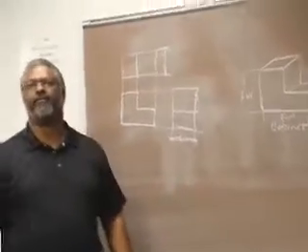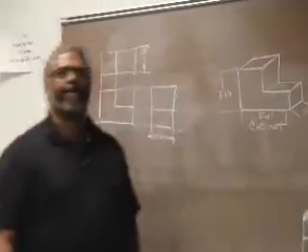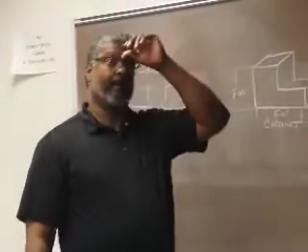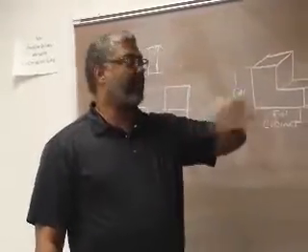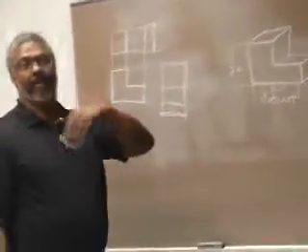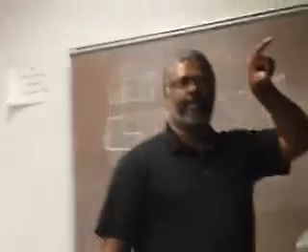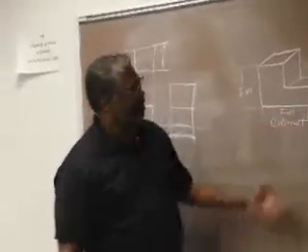Also, when we do these drawings, I know they can be cavalier, cabinet, or general, but where do we put that on our drawing? Oh, you can put that in your title block down there. In the title, you can just say cabinet and the angle at which you're drawing it.